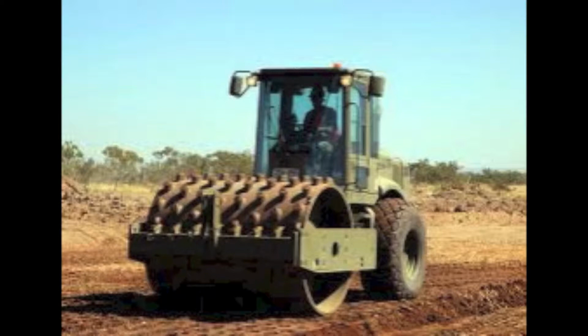Field methods that measure dry density and water content, such as the sand cone, nuclear density gauge, and drive sleeve, are capable of measuring density in situ. The field values are always compared to the lab value, maximum dry density, and optimum moisture content to ensure adequate compaction and moisture.